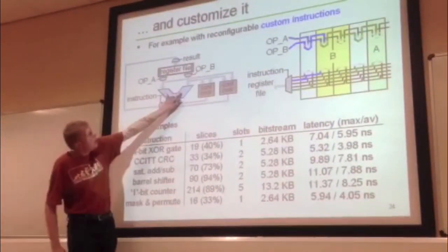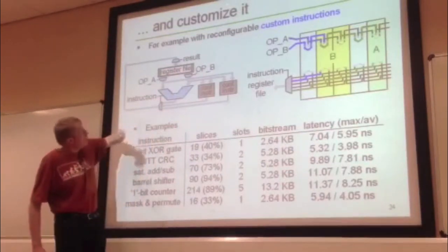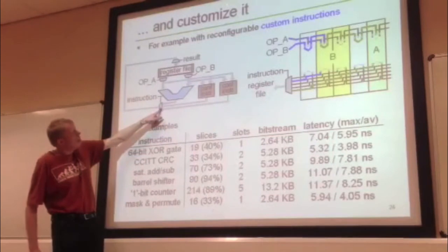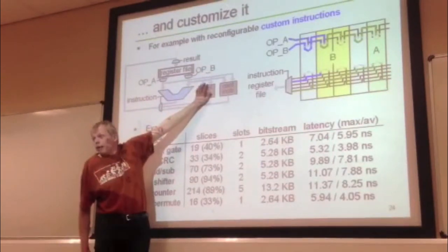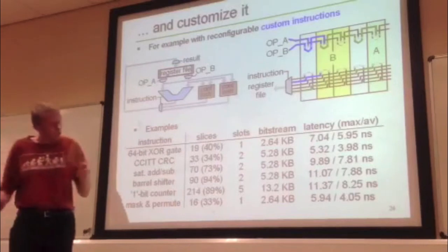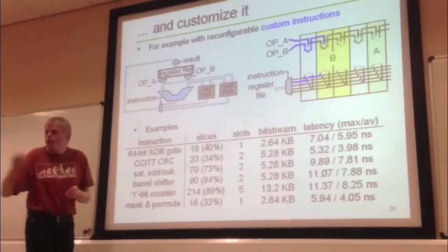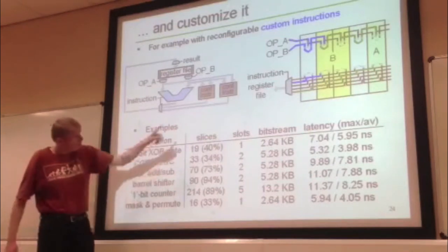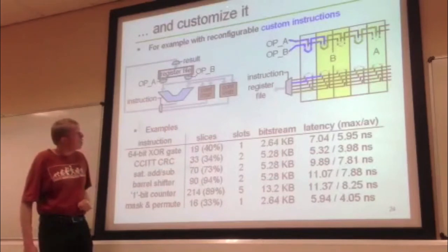If you say that's your ALU that gets the 2 operands A and B, what you could do is, well, you simply add a multiplexer, and you can add your own instructions. Yeah, you can have customized instructions. For example, if you do crypto algorithms, you have a lot of bit shuffling algorithms, or the S-box lookup, for example. You could have a dedicated instruction for this. And this gives you quite some speed up.